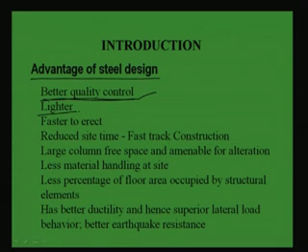Another is that it is very light compared to concrete structures. So the dead load of the structure, or the self weight, whatever we call it, will be lighter, right. Another is that it is faster to erect; we do not need to wait for curing of the concrete and for settling of the concrete cement, so we can simply erect it. Then reduced site time, fast track construction. If we want to reduce the time for construction, then we can go for steel design.